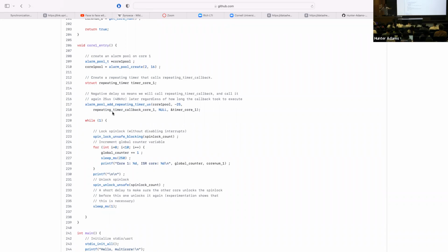And the scheduler that we're using has been modified by Bruce, so it is intelligent enough that when you add threads to the scheduler on core 1, it knows it's on core 1. So when you start the scheduler, the only threads that are being scheduled on core 1 are those that you've added on core 1. And likewise for core 0. The scheduler knows whether it's on core 1 or 0, so any threads you add to either core run only on those cores.